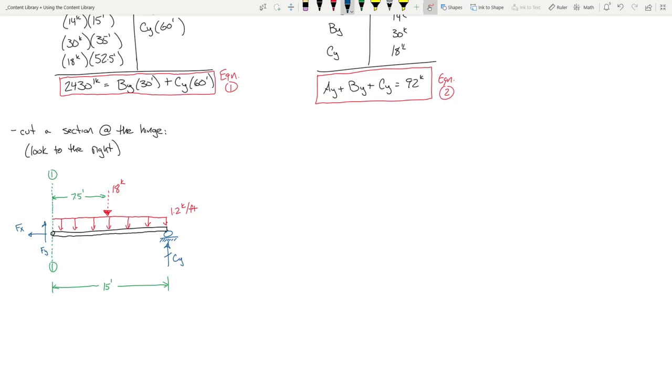That's the value, yes. The reason we don't include a bending moment reaction is because it's a hinge. We know there's no internal moment at a hinge. You're exactly right, okay? If I were to cut a section at any random arbitrary point, there would be a moment. You are 100% right. We will also find this when we draw moment diagrams for structures with hinges, we will find that the moment diagram crosses zero at the hinge. Cool. It'll be a check for us to see whether or not we're doing it correctly.